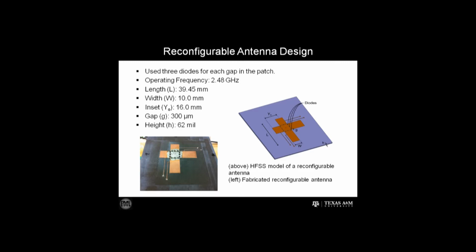The antennas are also designed to be reconfigurable. This means that with a flip of a switch, the antenna can change its polarization by 90 degrees. This is done by using diodes as switches. Arm 1 of the antenna has diodes pointing towards the center patch, while Arm 2 has diodes pointing away from the center patch. Arm 1 will be excited with a positive bias, and Arm 2 will be excited with a negative bias. This bias is determined by the user through a graphical user interface, delivered to the antenna through a microcontroller and switching circuit.